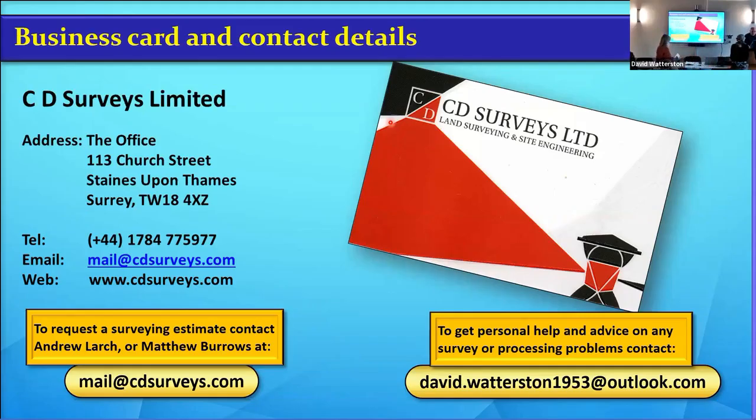So in January, I'm going to show you how to do leveling. You relate the levels to the site, and then establish, as I said, 2 or 3 datum points, whether it be a gully or a manhole or a corner of a building. Make sure it's stuff that might not get moved. Once you get them, the levels are then related to the benchmark. Right. Anything you continue, you're not going to go back to the check.